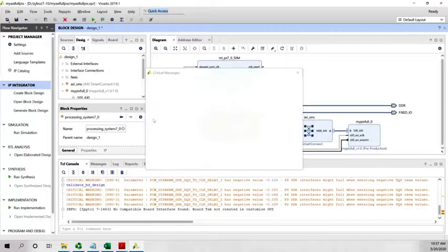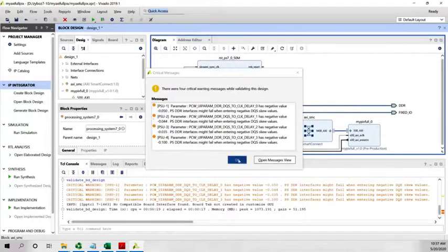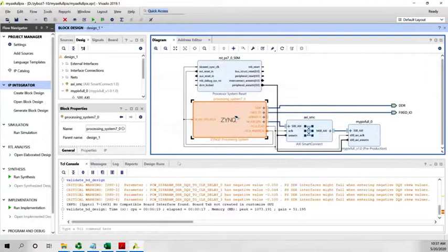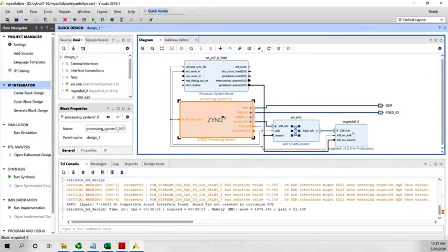So this process should be easy. But remember, it might be possible that you want to do this for your final project. It might be that you want your peripheral to be tied to LEDs as well. Well, in that case, just use the steps laid out in tutorial number 2, I think. I also posted a link to the tutorial of the Zynq book. They also tell you how to do that. Remember, you have to edit the XDC file. It was a bit messy, it was not fun, but it is entirely doable, by the way.